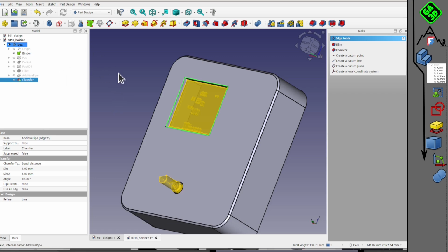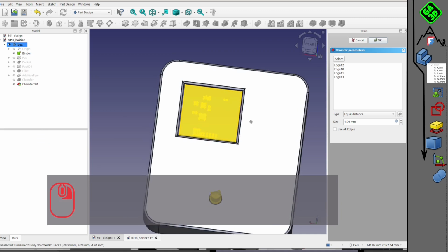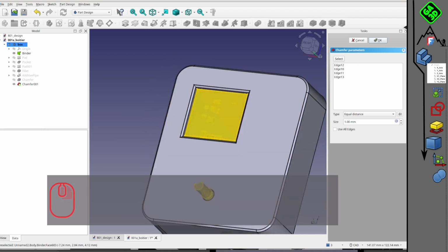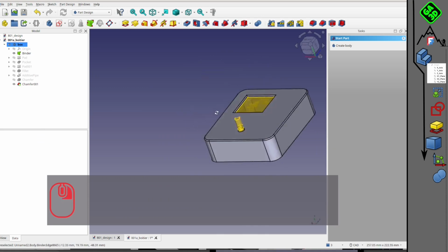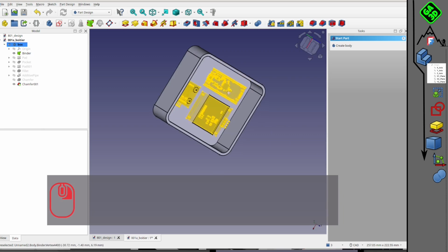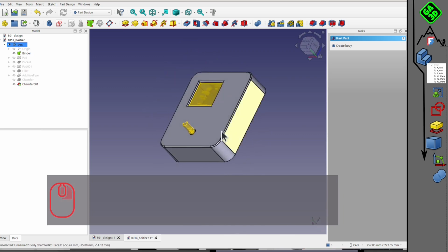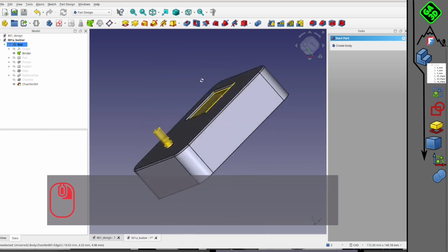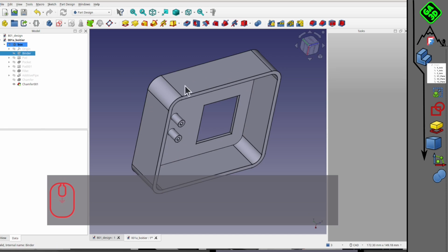And you have your shape binder, which is the ghost of assembly of your parts, which allows you to understand in fact where the external elements are. You do not have to display it, so you really see the piece you've created. But working like that, you're sure that when creating your part and wanting to use it, it will be consistent.